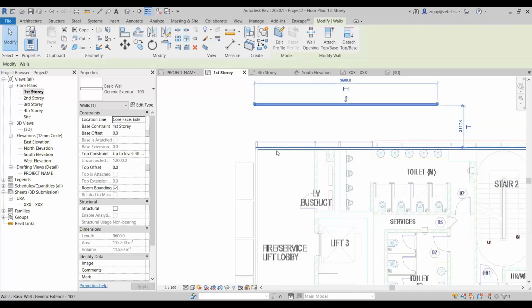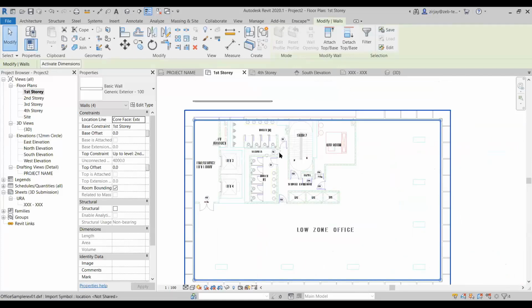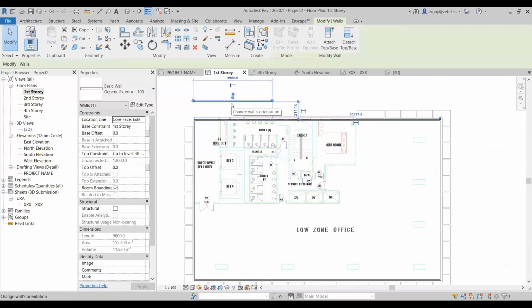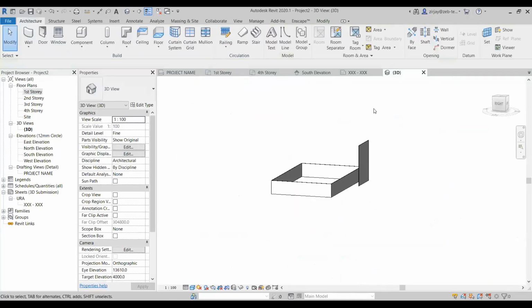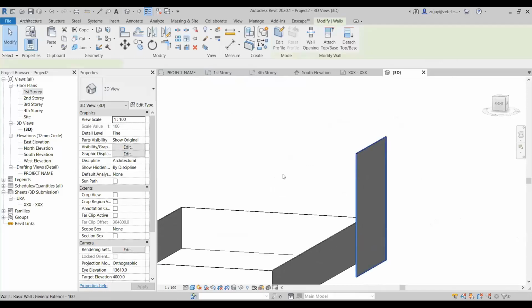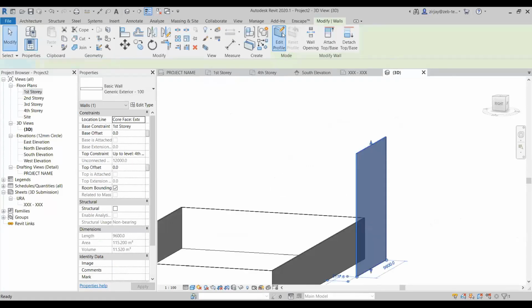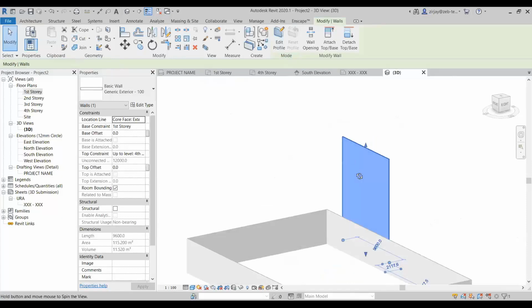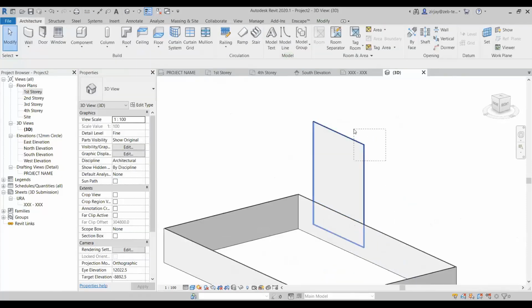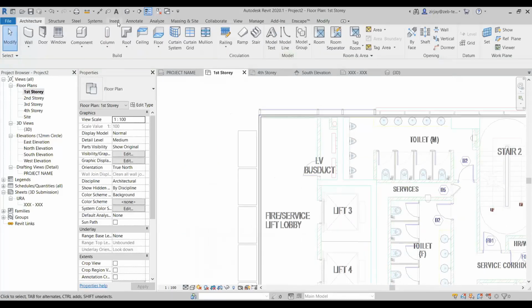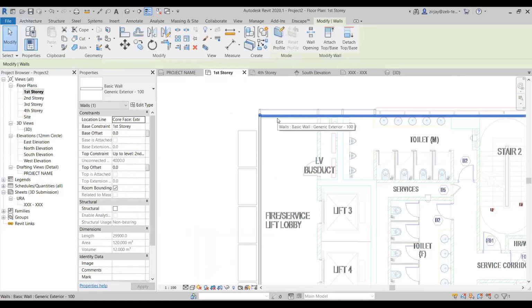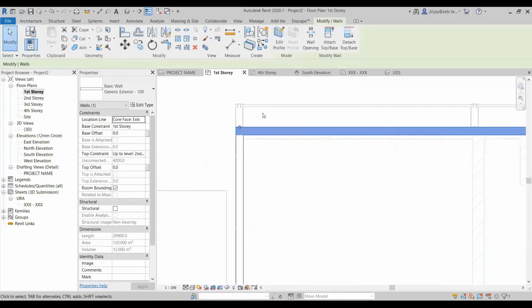Anyway, we're gonna group this particular floor eventually, and we'll just copy that group, sort of a block in AutoCAD, so that once you edit one block, it will apply to all the floors. So we avoid having these types of walls that go from first story to fourth story. It makes it easier for IES to read the information this way. And it's also the practice in Singapore. When you're building models, they always tell you to do it this way. So we apply the same principles when we're doing our analytical models.